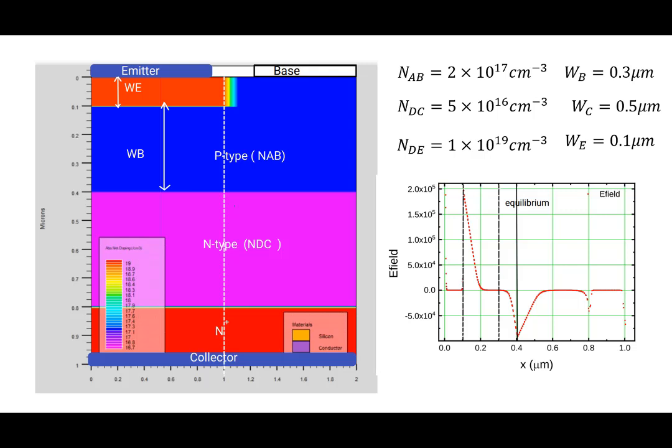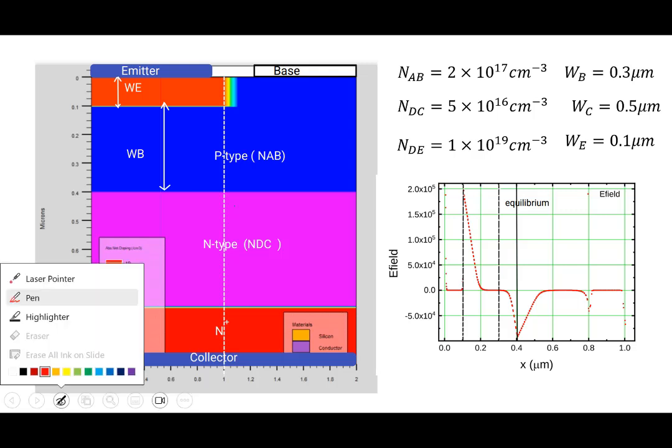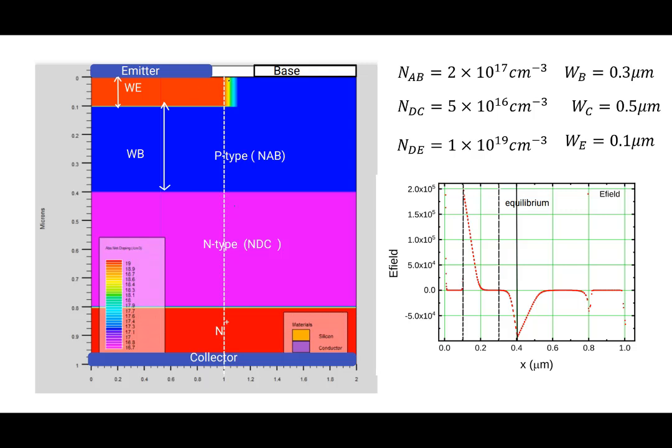So this is the two-dimensional view of the transistor. Note at the top here is the emitter. This is the N plus region here. Then underneath is the base region. All this is the base. The blue is the base region, and all this purple is the collector region. And then, in order to make contacts, you need an N plus region also. All right, so that's our transistor.